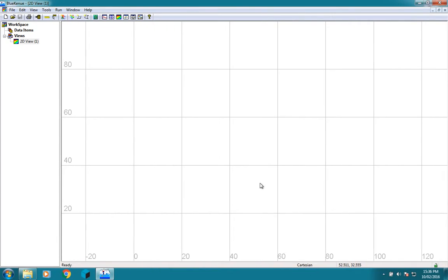In Practical 5 today, we're going to use Blue Kenue to examine, first of all, more sophisticated visualization of model results. So we're going to do things like sync 1D and 2D views, extract and plot velocity roses, look at residual currents, shear stress maps, and then we're going to compute and plot sediment mobility. And then in the second part, we will compare two model runs.